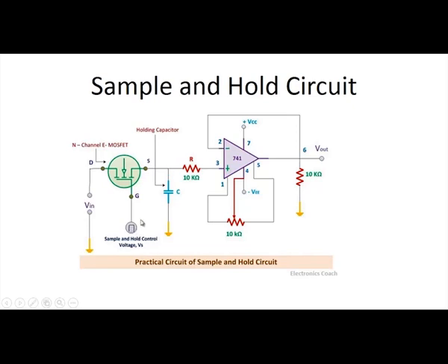When the pulse is negative, the capacitor holds the previously sampled amplitude of the input signal, and the capacitor's voltage is given to a voltage follower circuit. This has the output fed back to the negative terminal of the operational amplifier, and this circuit is a voltage follower where the signal is given to the positive terminal. This voltage follower is otherwise known as a unity gain feedback circuit.